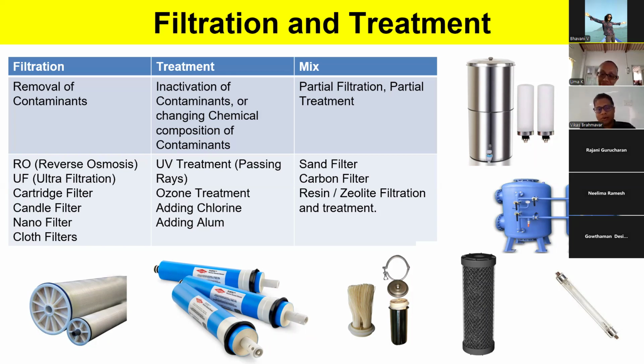unnecessary filters. See, I'll tell you why. So someone puts a sand filter. You have silica leaching after 10 months, 12 months, possible based on your incoming water. There will be silica leaching coming out. So it does more harm than good in some cases.